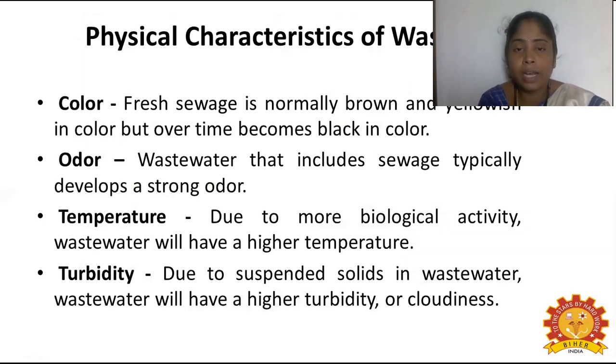Or yellow in color. But when it has been fermented, or has taken a long time accumulating in a particular area, the color will turn black. That is why we can study whether this is wastewater or fresh water. Fresh sewage is normally brown or yellowish in color, but when it takes a lot of time, it turns black.